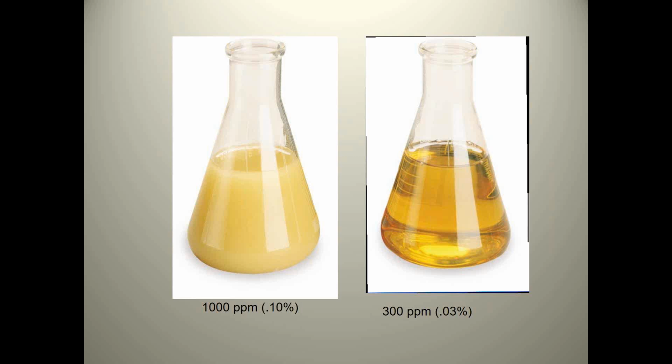It starts getting the little fine bubbles in it. Now, in a hydraulic unit, it could get foamy and look like this for another reason, and that means you're out of your anti-foam in the hydraulic oil. But this one here has 1,000 parts per million of water in it, and may also be from a hydraulic unit that is out of anti-foam.